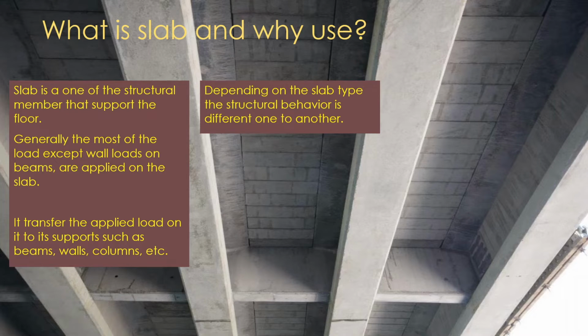So the slab is the most widely used element to carry the floor load to the beams or the supports. It transfers the applied load to its supports, such as beams, walls, or columns. Depending on the type of slab, the structural behavior is different from one to another. There are different types of slabs, but generally the slab is the most widely used element or the area filler in the structure.